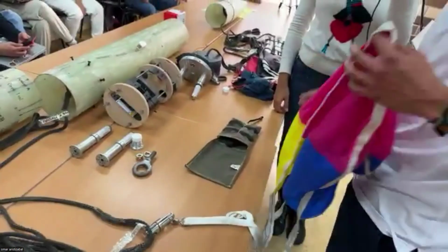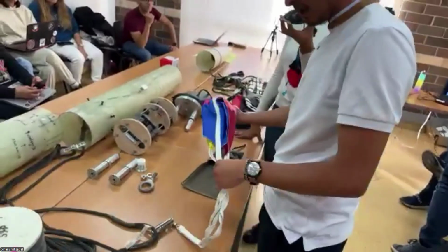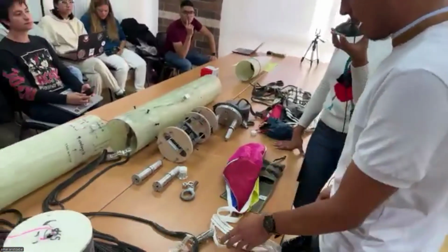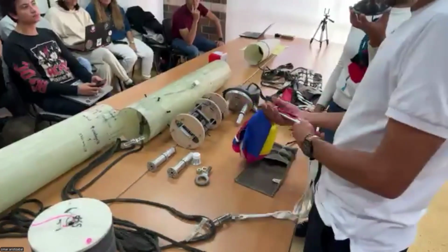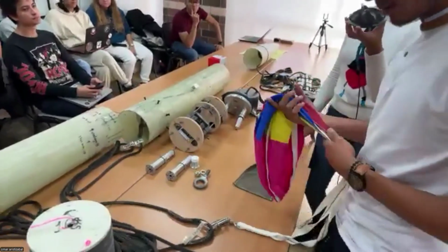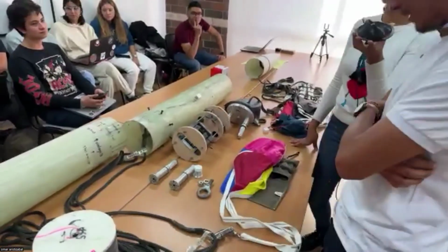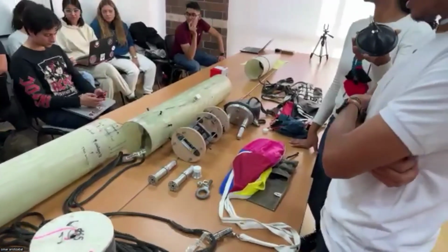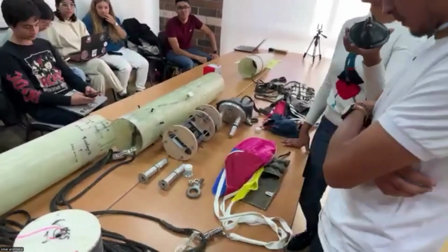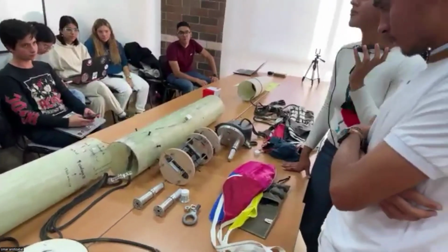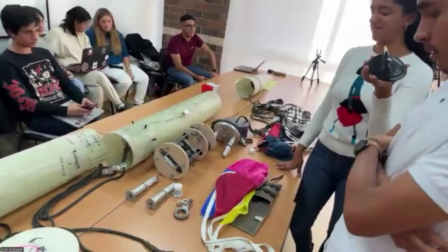It allows us to descend at a fast descent rate because in all the design process we wanted to obtain a minimum horizontal drift. So this parachute descends at 38 meters per second. We're going to tell you now how much that is in feet per second. It is slightly below the ESRA limit, which is 40 meters per second. It's 124 feet per second. Okay, thank you.